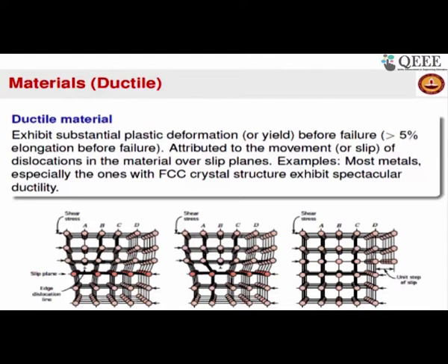Okay, so the underlying microscopic differences which cause a material to be ductile or brittle are the presence of dislocations and the number of slip systems in the material, allowing these slips to move around. Obviously, if there are more slip systems, the dislocations can keep moving in different directions and different ways, because of which you can draw these metals into thin wires and sheets. Whereas for other materials, like magnesium, the dislocations will not be able to slip. Because of that, they will fail in a brittle manner.